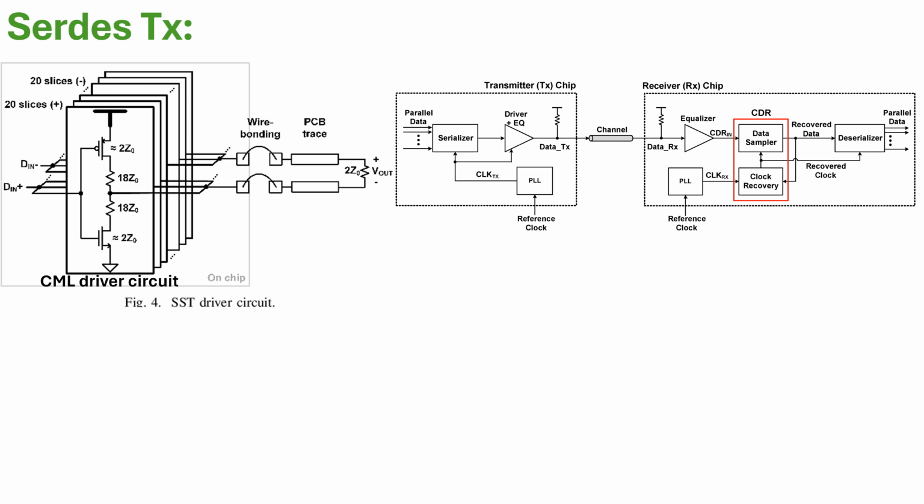Source series: look at the 18 ohm resistance, or sometimes 50 ohms. It's programmable anyway. These are in series with the source, and hence the source series termination of 18 ohm is a termination resistance in series with respect to the source. So that is a source series driver circuit. It's a kind of transmitter IO used in the serializer part, or transmitter part, of the SerDes.